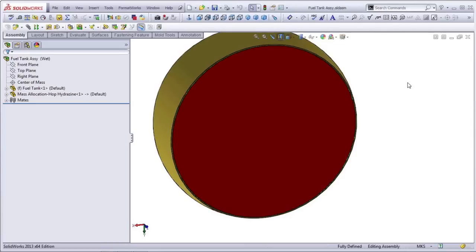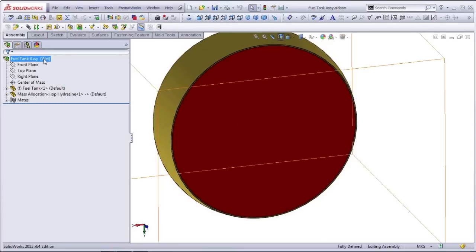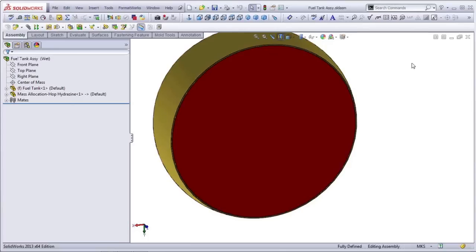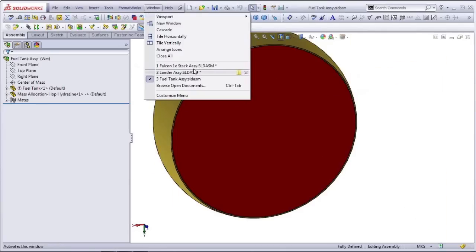as needed as the assembly changes and as the layout changes and the propulsion system changes. But this mass inside goes with every tank assembly, and that's why the moment of inertia increased pretty significantly, because if it were just the fuel tank, it might not have made as big of an impact. So that's how I do those.